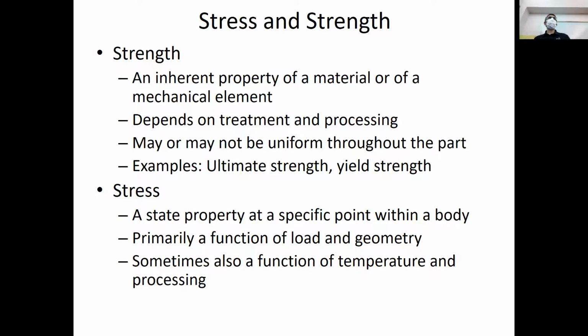The strengths may be affected by treatment or processing, unlike the modulus of elasticity. So this could be affected by treatment and processing. It may or may not be uniform throughout the parts. There could be some slight variation. On the other hand, a stress is really a state property at a specific point. And I really want to emphasize that.